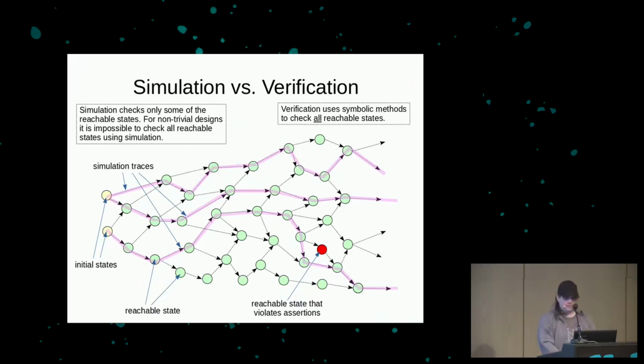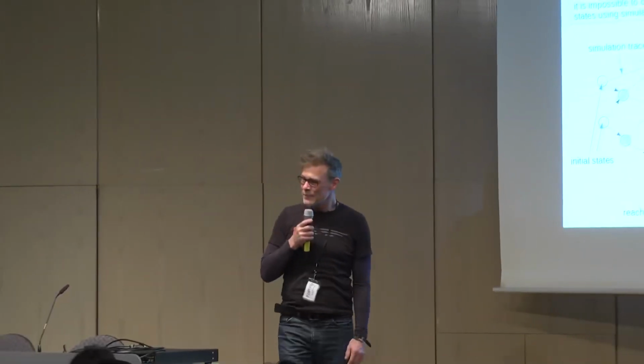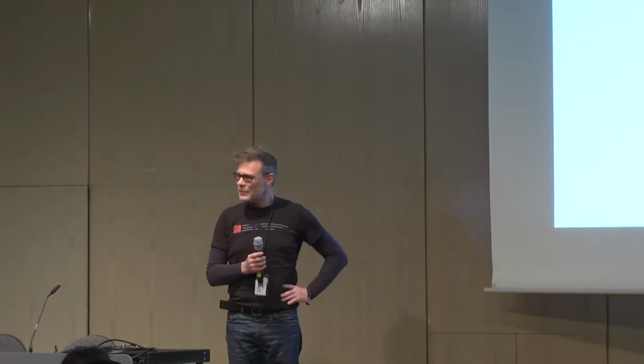Someone else? Yes. I'm wondering if in your experiments you have actually run into problems with vacuity? That your assertions hold because you have artificially restricted the state space too far? Yeah, I mean, this is possible. Whenever you use restrict or assume, you have this risk that you've restricted it in a way so it doesn't really work anymore. So in a usual workflow, you often have some Verilog defines or whatever in your design that you can use to artificially add bugs. And then you always check that at least you still can find those bugs. Of course, this is not a guarantee, but at least it improves the situation a little bit.